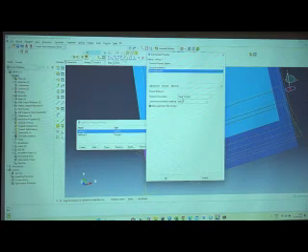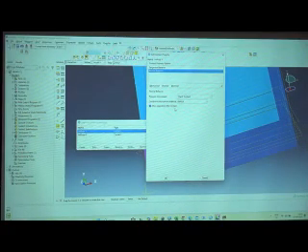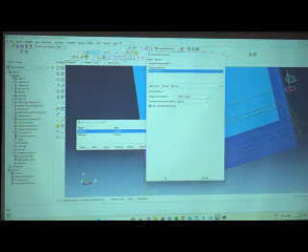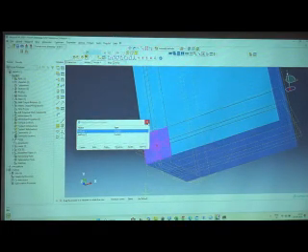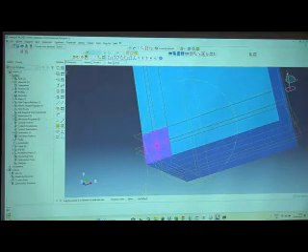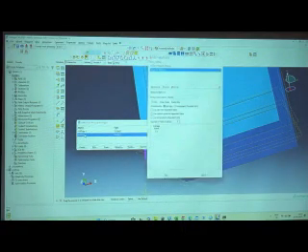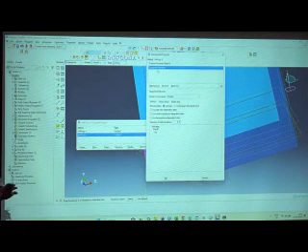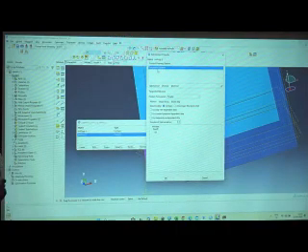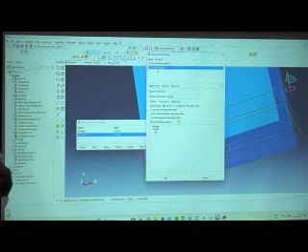The normal part is hard contact, and allow separation after contact. As you said, sir, if I apply the lateral load, separation is allowed. It is allowed by default. And for the pile, I used only the tangential behavior, because my soil is a soft soil, so it is a friction pile, and only the tangential behavior will be there. So I am using only this tangential behavior.